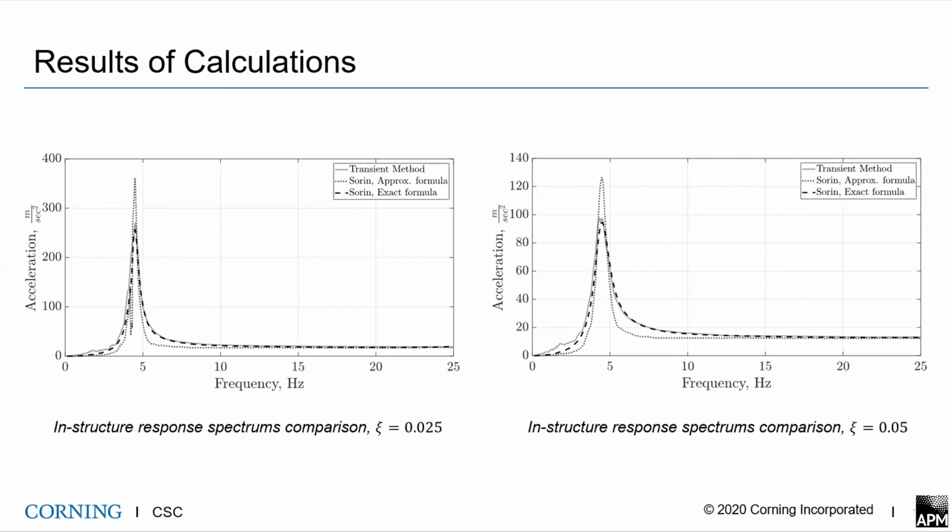Yeah, I understand the question. Unfortunately, the response spectrum method is applicable only to linear structures, so nonlinear effects cannot be taken into account, because here we should perform the mode superposition procedure. We can't perform this procedure for a nonlinear model, unfortunately.